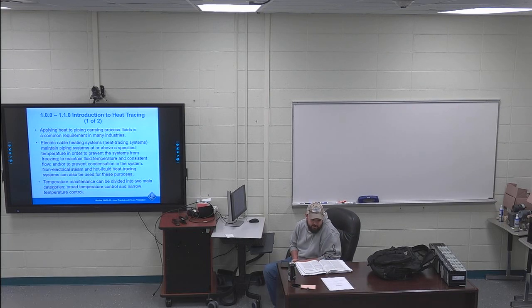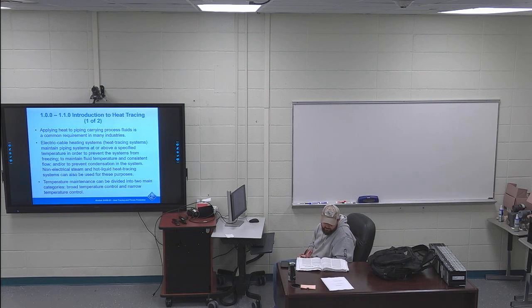Moving on to page 3, the whole second paragraph, or the first full paragraph, right after where you see the parallel resistance heating cable. That is all highlighted. So I'm going to read through this paragraph and then go back and tell you what to key in on. Self-regulating heating cables produce heat from the flow of current through the polymeric core or fibers. In both types of cables, the number of electrical paths between the bus wires changes in response to temperature variations.